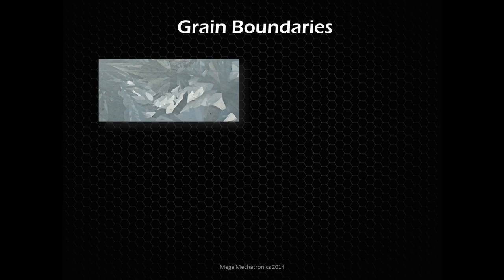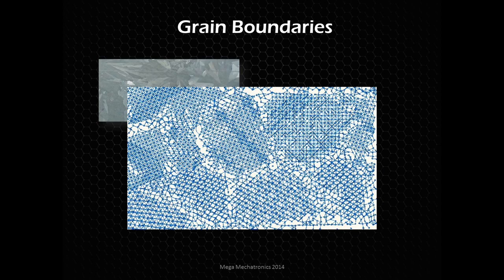And when these crystals start forming randomly within the material, they're going to be crystallizing in different orientations to each other. This is an example of a galvanized surface, and that zinc is crystallizing in different orientations, and then we see the light refracting off of that in different ways, and we can easily make out the grain boundaries.